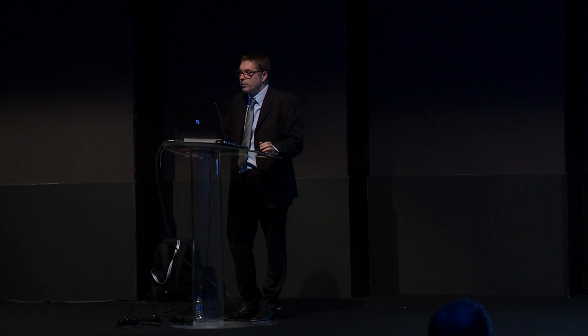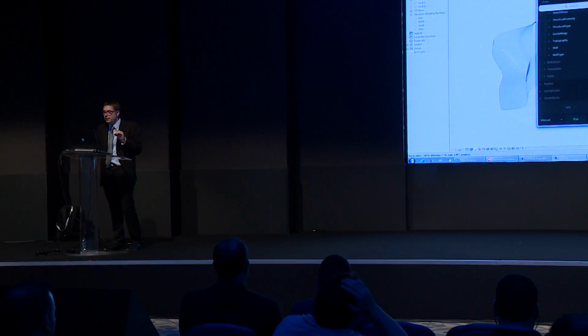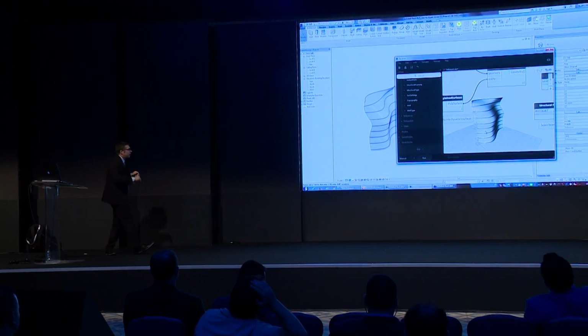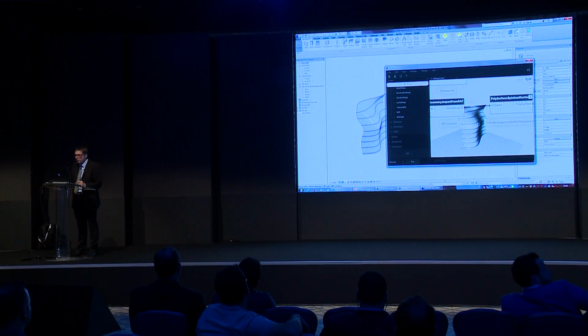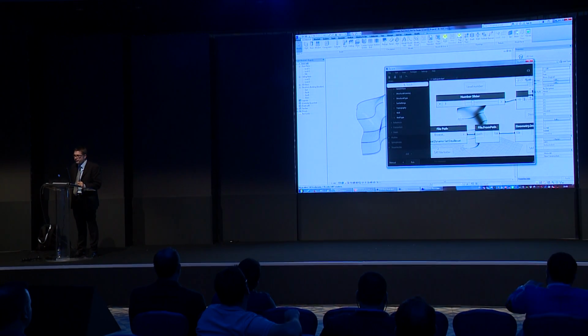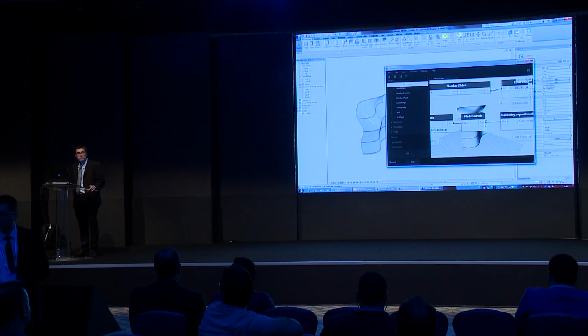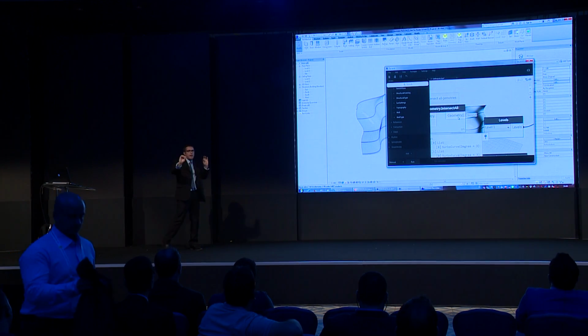I will use this geometry intersect all. That means if I remove this, connect the plane into the geometry input and put polysurfaces into entity, and run it, as you see in Dynamo, you cut your SAT file with a horizontal plane. If I put fewer planes, I run it, I get less intersection. Easy.